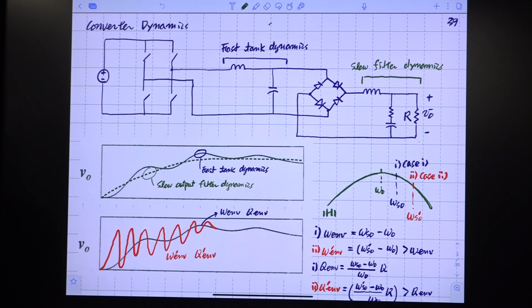They are entirely different things, but the external shape or term is the same. Both of them are called frequency, so it's very confusing. But you should have a clear distinction between switching frequency and modulation frequency, the same as you have a clear distinction between duty ratio and switching frequency in the PWM converter case. That is very important.